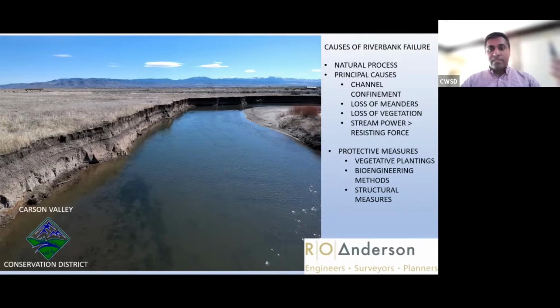And part of the reason here is, we don't have a lot of vegetation on our river banks, especially through Carson River. It just doesn't really grow much here. You can't expect these river banks to have the nice looking vegetation that you would see elsewhere in the country. So obviously that's a problem here. And like I said, most of our projects implemented structural measures with some bioengineering methods, as you can see in later slides.